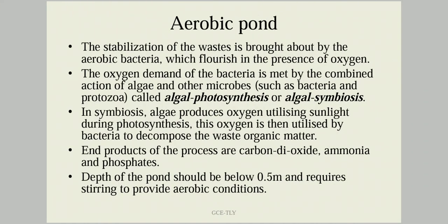In the aerobic pond, stabilization of waste is brought about by aerobic bacteria which flourish in the presence of oxygen. The oxygen demand of these bacteria is met by the combined action of algae and other microbes such as bacteria and protozoa. Hence it is called algal symbiosis.